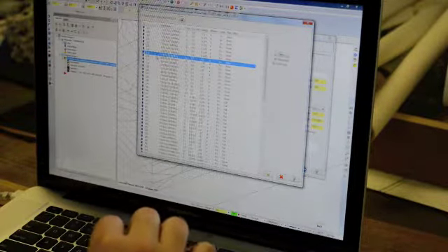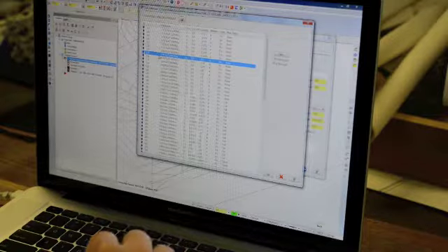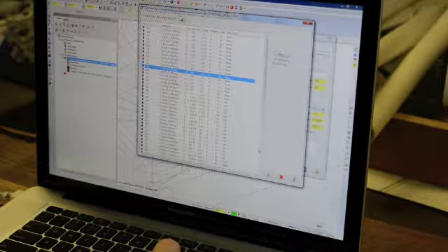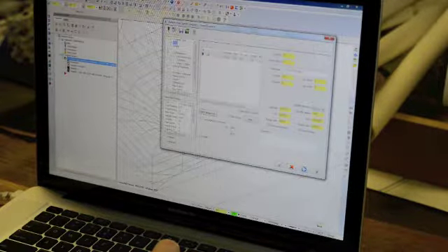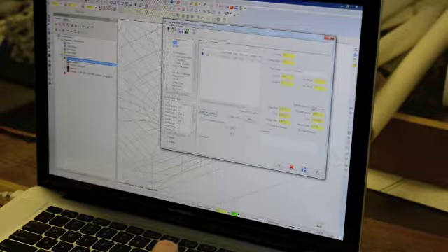So we have a piece of hardwood we're going to mill, and we want to do our rough cut. So we're going to want something beefy to do that. So we'll go with a 1/2 inch flat. We'll try that out. So press OK. Then over here, it's going to want information about what you want the spindle to do.